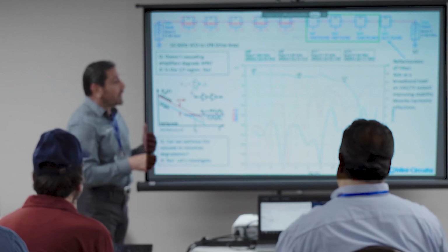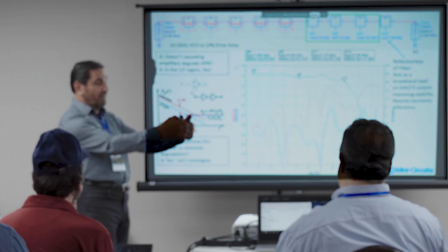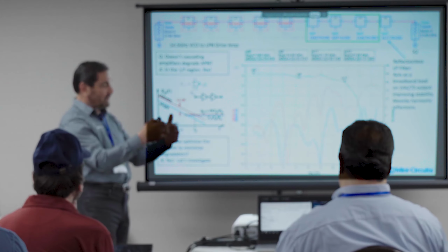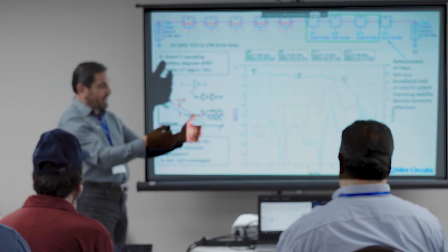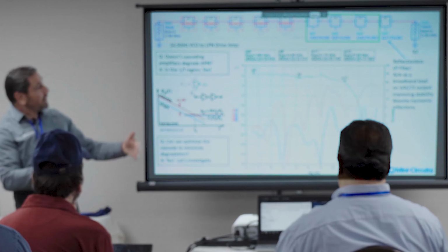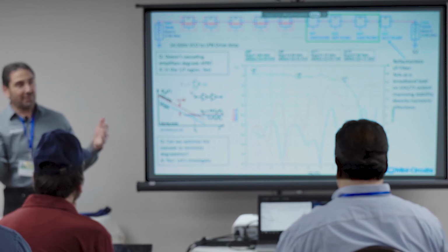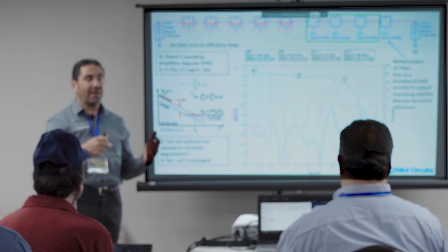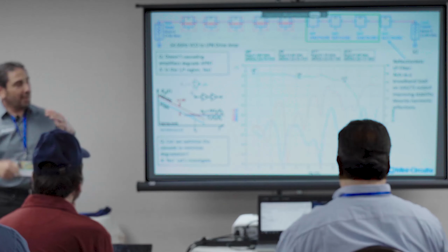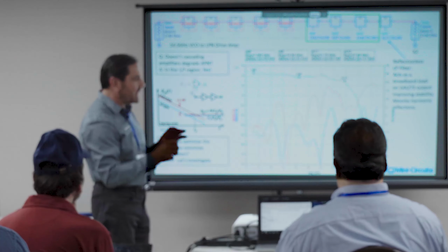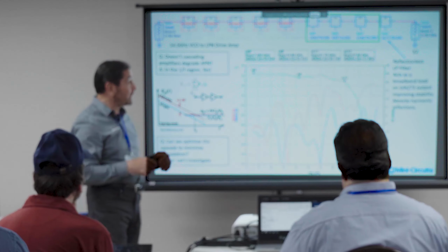But the same thing. You have this ×2 multiplier following that. It's nonlinear. You don't know what the impedance really is, and it's going to have harmonic content that's going to come back. Well, this will absorb it rather than just reflecting it back in and having these spurious signals bouncing around and giving you ripple, amplitude fluctuations, and phase fluctuations. So it's a great way to terminate, again, as a frequency selective attenuator.